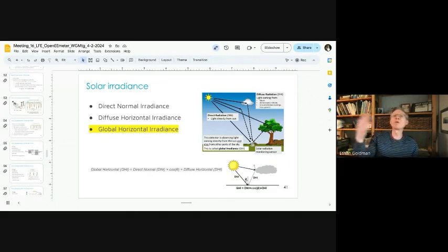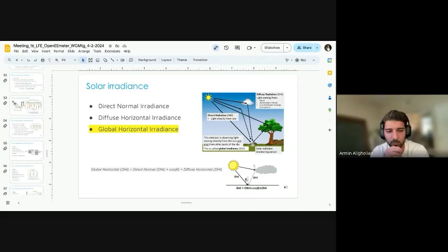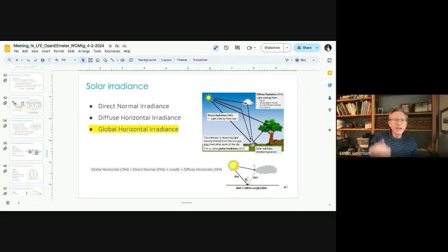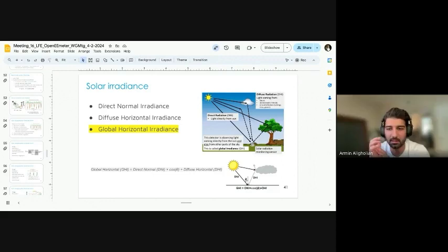Obviously, if only one hour of the year is saturated, we don't expect that finding a day that's 10 degrees hotter suddenly does something clever. But if we had a system that's saturated 10% of the time in the summertime, why wouldn't the model predict that? We could look at a saturated PV system and compare model versus actual. A dumb model will make a nice sine wave in the middle of the day, and maybe this model will actually show a ceiling and cap it off. Is that a reasonable assumption?